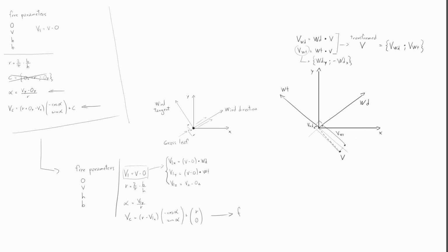And after, we'll have to recompose everything in our usual coordinates. Since Unreal uses the z-axis as up vector, this last bit could be confusing, but essentially the 2D x-axis has to become the first two components of the final 3D vector, while the 2D y component will directly correspond to the z component in 3D.